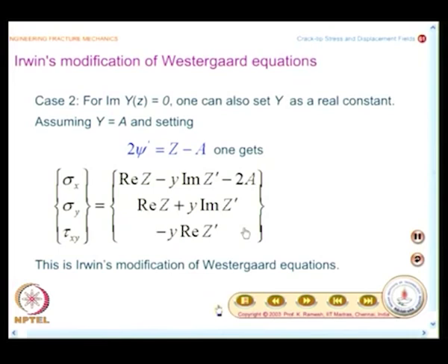And in this, what we saw, it prominently showed forward tilt of the fringes or backward tilt of the fringes, whichever way you take the sign of sigma naught x. And this models short cracks. In the case of SCN specimen, it is forward tilted. In the case of RDCB specimen, it is backward tilted.